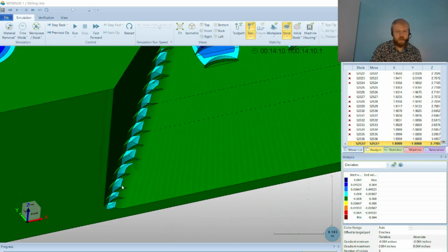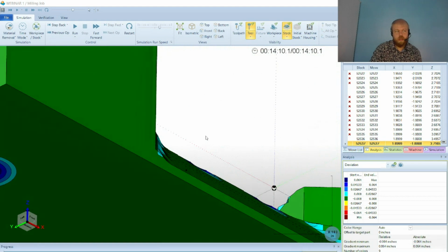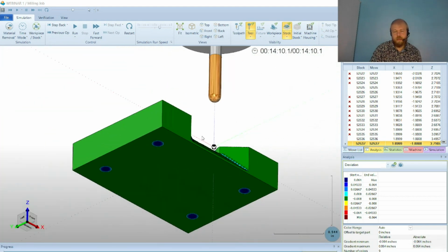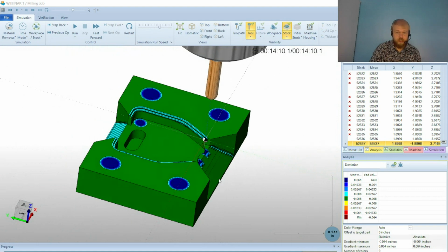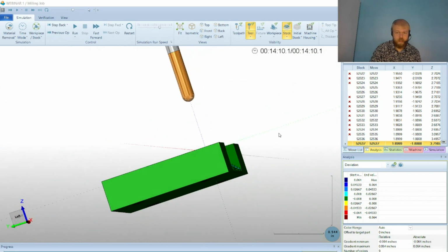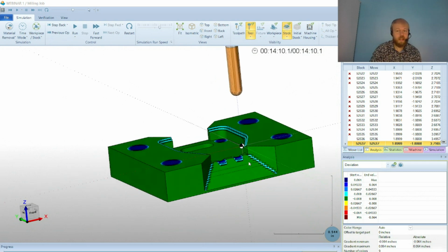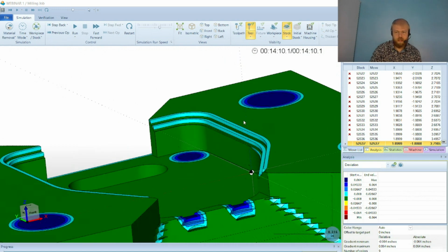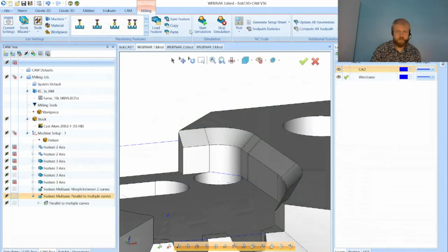So yeah, as someone was mentioning earlier, the ball end mill isn't able to get into this corner. So really the only way I could see this being machined on that corner there would be if we changed the machine setup to have it tilted along that angle to be able to use a flat end mill in the corners there. That'd be the only way I could see doing that. And we'll take a look at an option for that in our next part file that we're going over. I didn't see this one here. Let me turn that parallel to multiple curves on as well.